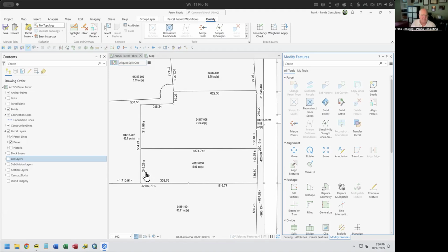Again, especially telling you that this was 250 feet, but in fact, it actually computed the actual distance along here was only 249. This was 319. Now, why that seems strange because this should be 250. Perhaps it was because this original COGO distance was less, and it actually did a proration in that it said there is a proration that goes on here, so that is the resulting proration that occurred.